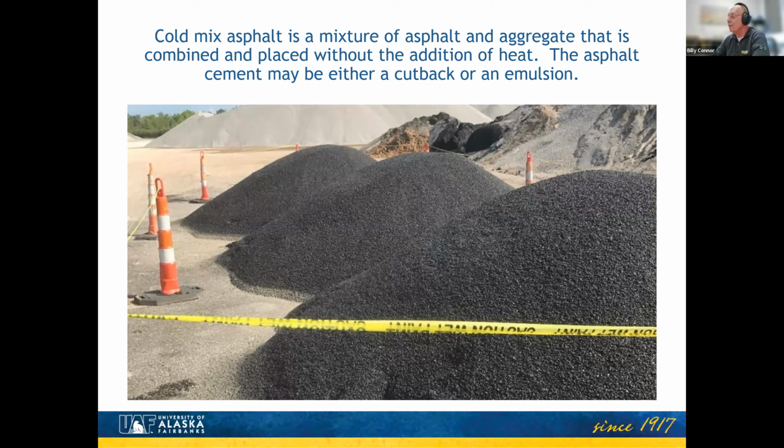And we've been playing around with those and been pretty pleased with some of these custom blends that are out there on the market. It's just that you always want to test these materials with the rock that you have and come up with a mix design before you use it. So there is that little step that you're going to have to go through.